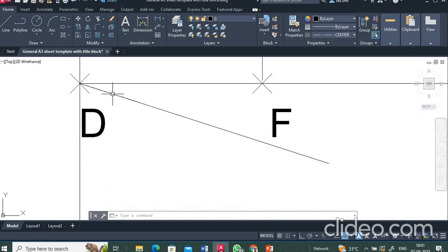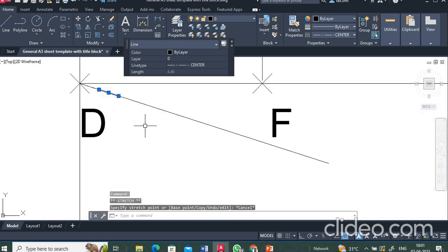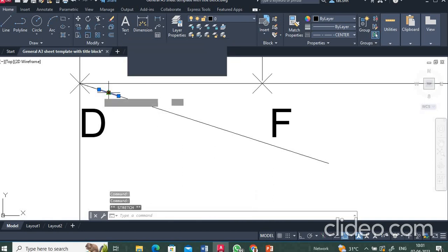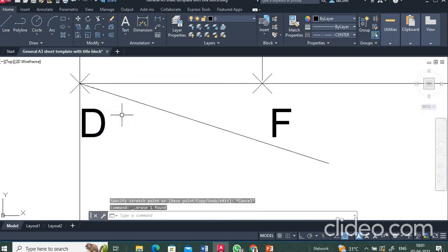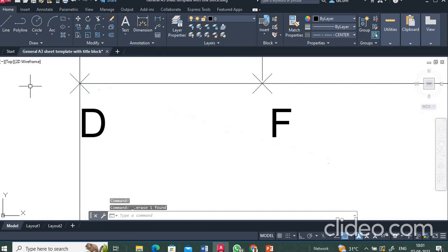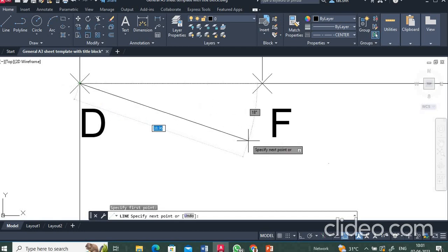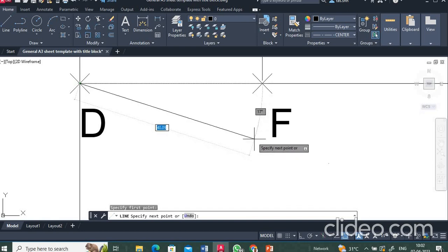Instead of doing that, what I do is take a 7 centimeter line, since I want 7 arcs. That will be better. I will take an angular line at any angle, of 70 mm or 7 centimeter, in multiples of 7.